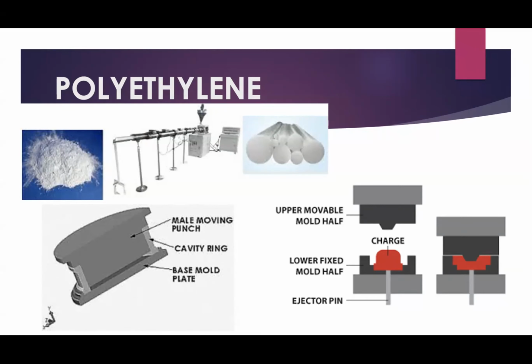The last thing to mention is that polyethylene exists in 2 forms: a crystalline form, which is more organized and gives you mechanical strength, but less cross-linking, and an amorphous form with basically less strength, but more cross-linking. The optimum crystallinity that you're aiming for is about 45 to 65%. If it's too low, it becomes brittle. If it's too high, you get no cross-linking, so it wears away very easily. And in terms of properties, it's got a similar Young's modulus to bone. It's ductile, it's cheap, and it's resistant to wear.